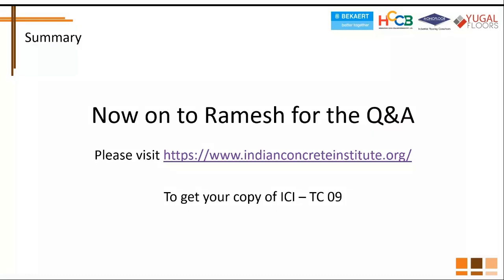this question needs some deliberation. This is the first challenge for me dealing with the RMC suppliers or the client. They get very uncomfortable when I talk about higher slump or higher water cement ratio. There are two things I stress enough in my presentation, but I would like to reiterate here. First thing is we need the concrete to bleed. For that, you obviously need water. We need it to bleed for two reasons. First, we want to prevent plastic shrinkage cracks. Second, the hardener needs water to bond, because we want to keep spraying water on the hardener to the minimum.